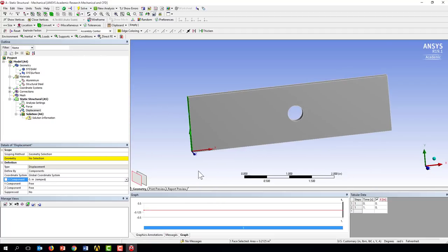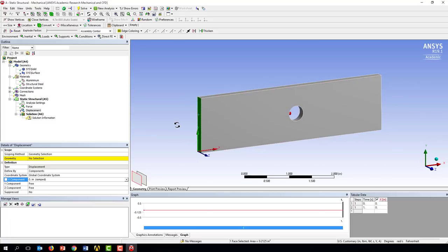Now if I just set x equal to 0, there's nothing to provide stability in the y and the z. Because this is a plane and it's not moving anywhere on that plane, that will prevent rotations, but it won't prevent a translation in the y or the z direction. So I need to constrain those directions as well.